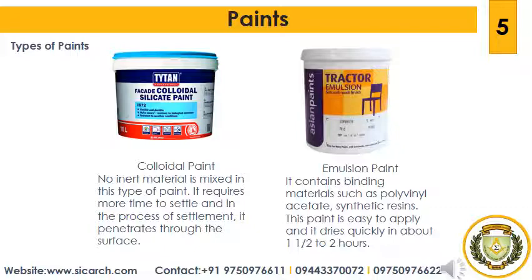The application of emulsion paint can be carried out either by brush or by spray gun. For long service life, it is recommended to apply 2 coats of emulsion paint. For rough cement plastered surface, a thin coat of cement paint may first be applied to smoothen the surface. It is necessary to have a sound surface to receive the emulsion paint.